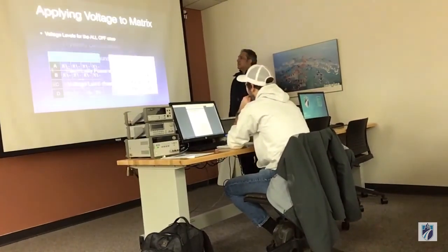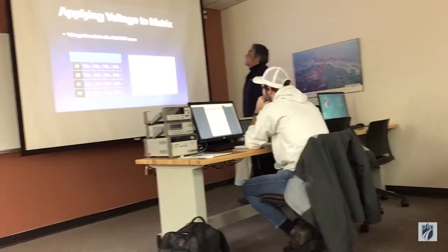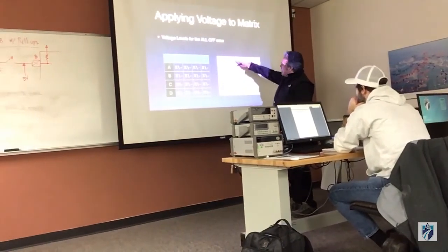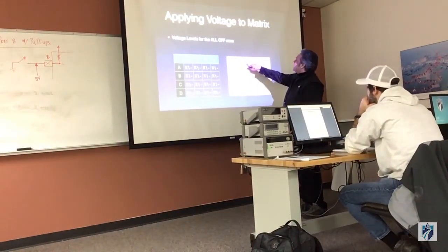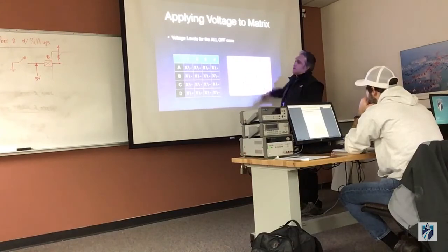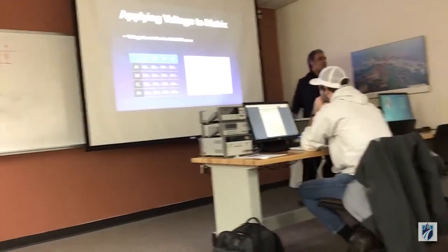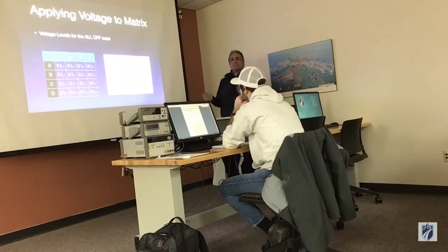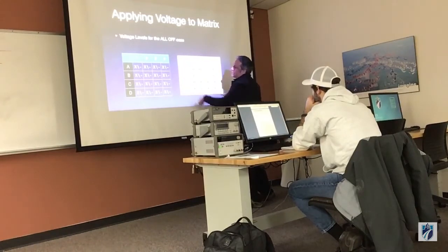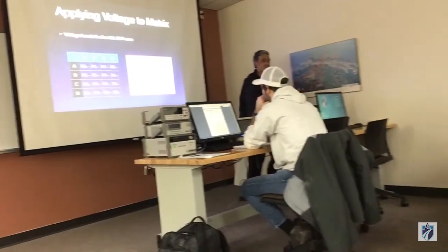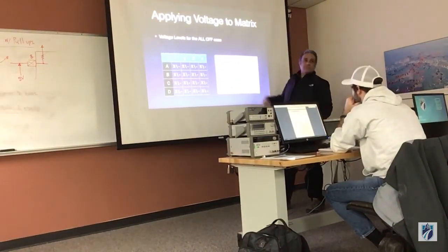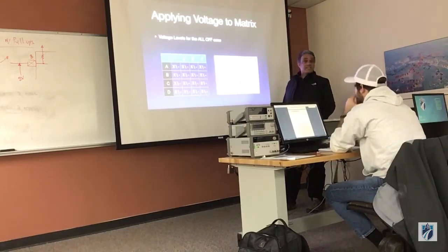Okay? All right. So here we go. This is how the all-off state looks. My columns are my common cathodes. So if I disconnect all the cathodes, maybe I just have 1, 2, 3, 4 transistors, and I take those transistors and I cut them off, right? I just electrically make sure that they're in shut-off mode. I will have no current flow regardless of the voltage on the rows, right? So by disconnecting these 4 guys, I automatically create an all-off condition. Right? Does that make sense?